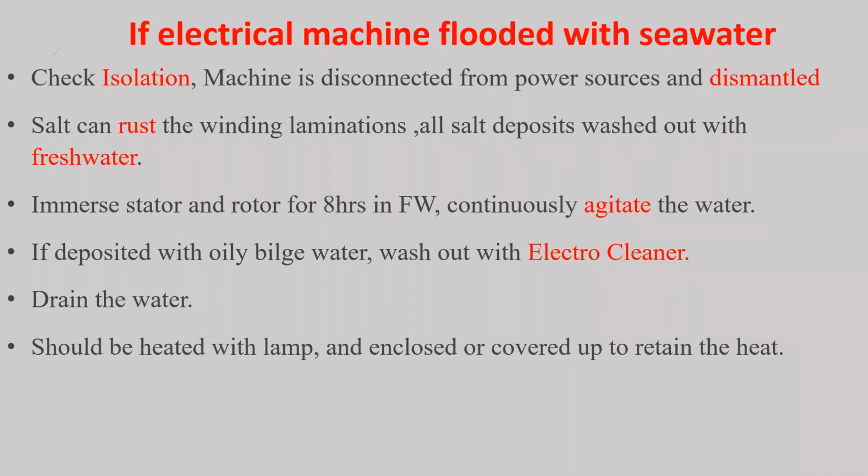You have to immerse the stators and rotor for at least 5 hours in fresh water and continuously agitate the water. If oil is still present in the equipment, clean it with electro cleaner and drain the water. Then heat it with a lamp and cover it to retain the heat. We can go for the next.